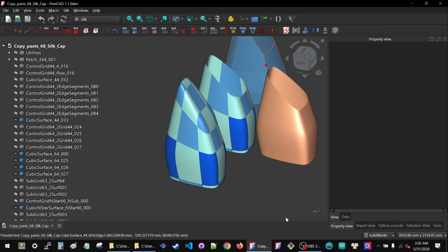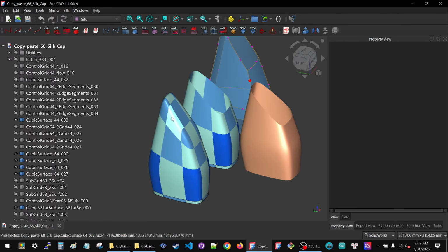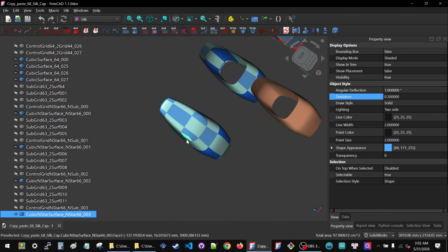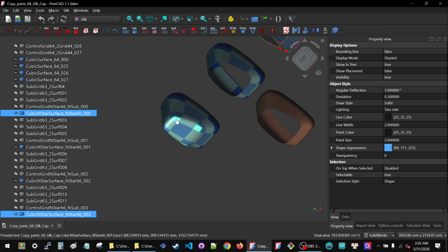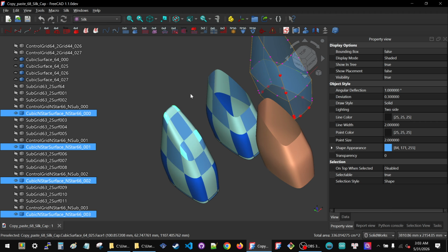In the last episode, we created this face on top by reusing the existing curves. We chopped it up, reusing all the existing cut points and line segments. And then we blended the corners with the same edge blend that we've already used before. And then we created these four new objects here, which unlike the dark blue surfaces which have four sides, can handle three sides, or four sides, or five sides, or even six sides, even though six is not recommended.